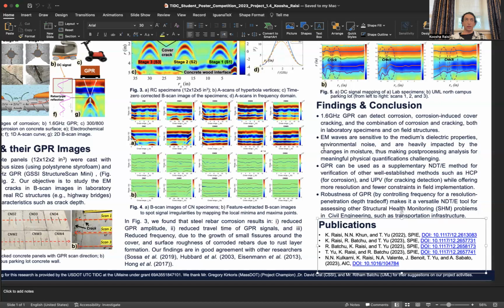Imagine you're in the field and you want to quantify a crack. You take images of something, you've solved all the problems. Tomorrow it's raining. The moisture content of today is not going to be same with tomorrow. And that impact is so influential on GPR that is mentioned almost everywhere. And that's always a problem. But that can be a good thing and a bad thing, obviously.